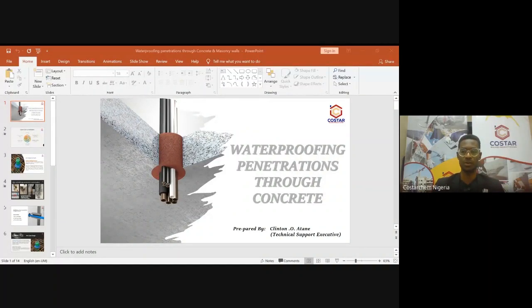When pouring the grout, you are to take note: you don't pour it all around. Artisans often make this mistake. When you are pouring it all around, you have a high chance that you will incur air bubbles inside the grout, and that is bad. The grout is specially formulated to flow under its own weight. You don't need to influence its flow. It flows under its own weight, self-leveling.